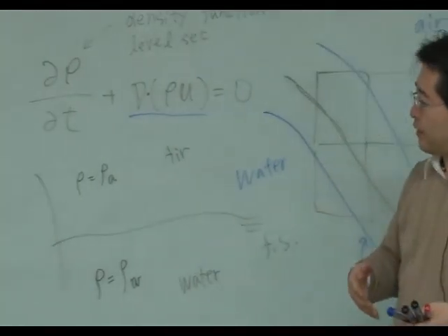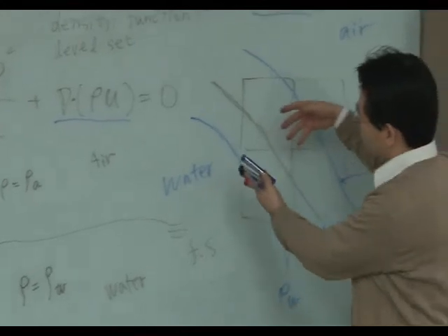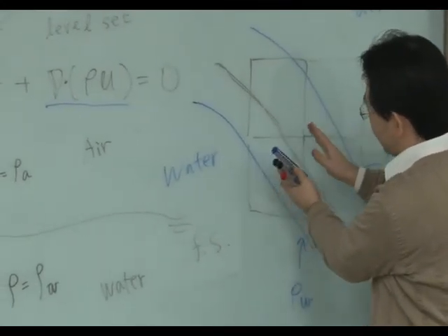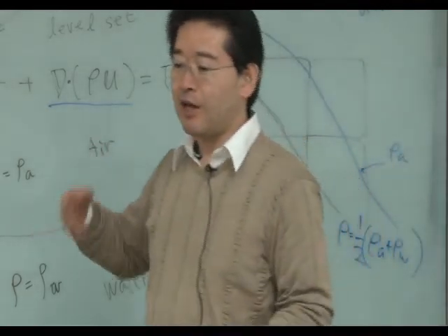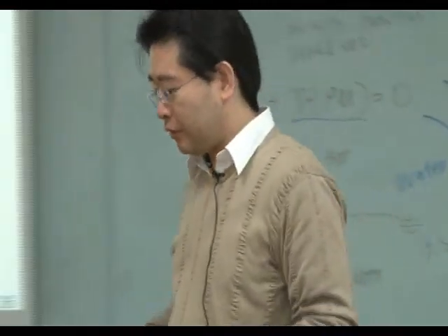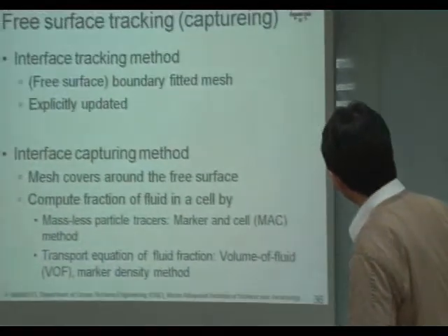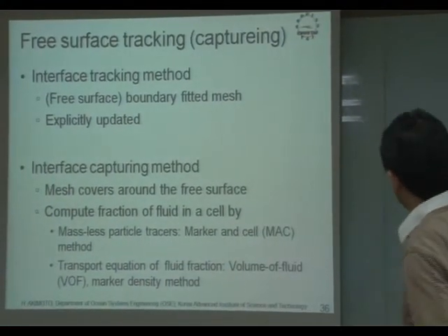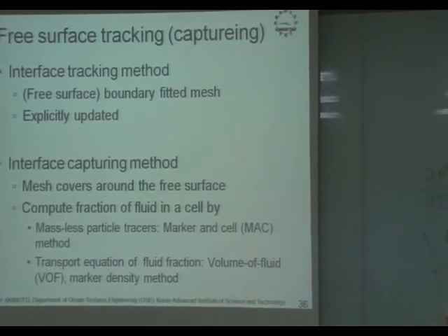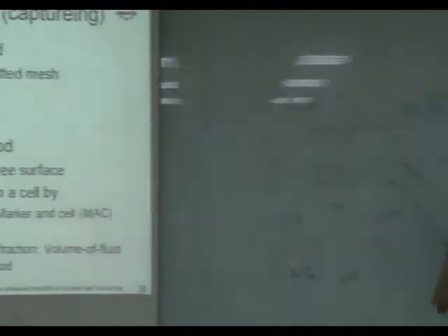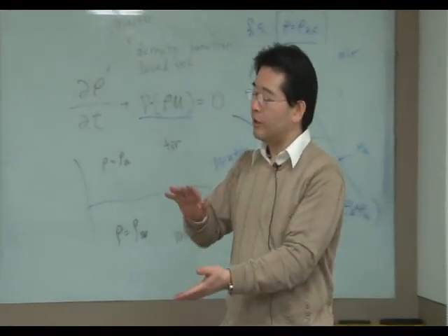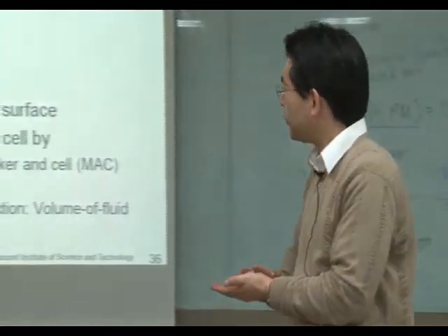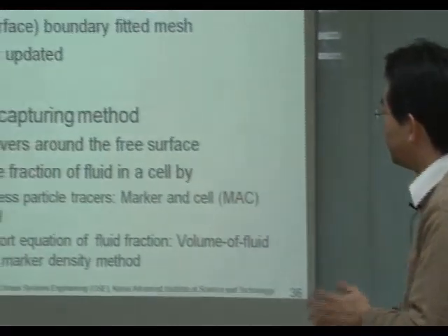Because of the upwind scheme, this thickness will be expanded according to the time development. So it needs another consideration to keep the thickness of this region in a limited size. It will be discussed in the next class.